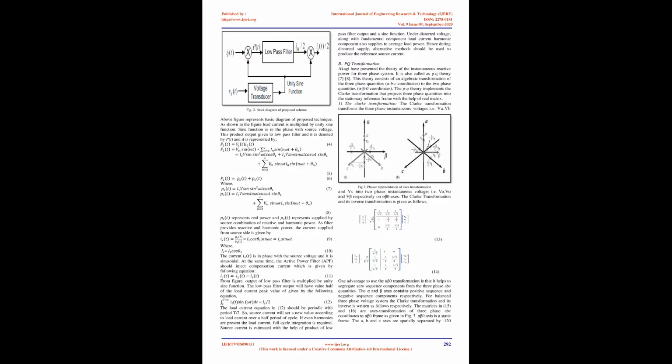A lot of conventional solutions to these problems have been introduced. Passive power filters and capacitors are the simplest traditional methods to lower the harmonics and increase the power factor. But the system becomes bulky because of condensers and inductors, and it also causes resonance, which makes the system more unstable. Later, static VAR compensators with several power factor correction configurations were added. But some SVC configurations have very long response times, so they are not suitable for fast fluctuating loads as well as harmonics of lower order.